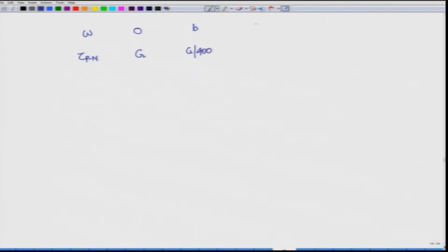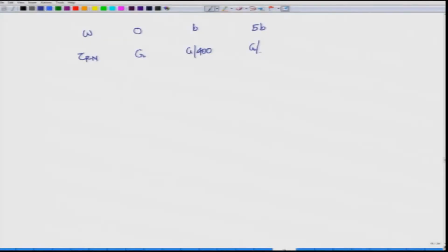If the width of the dislocation becomes 5 b, so what we showed here as 2 and 3 lines, now if you extend it to 5 b, the stress required or the resistance to move the dislocation reduces by orders of magnitude. So, here it is of the order of 10 to the power 3 and here it becomes G by 10 to the power 14. So, 11 orders of magnitude smaller stress is required if your width becomes like this.